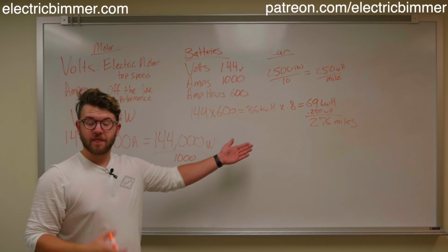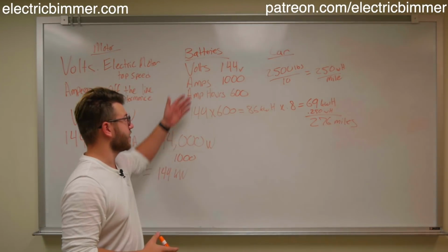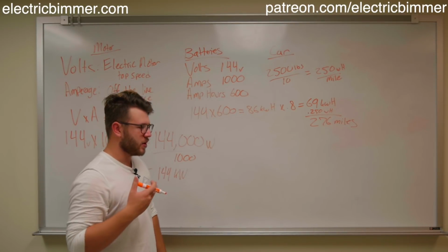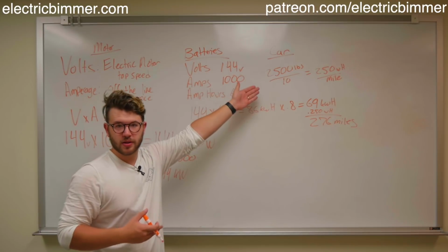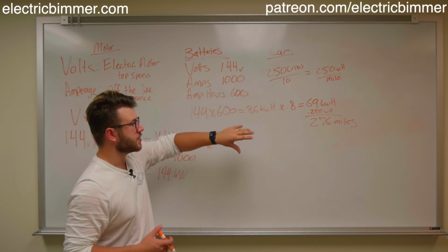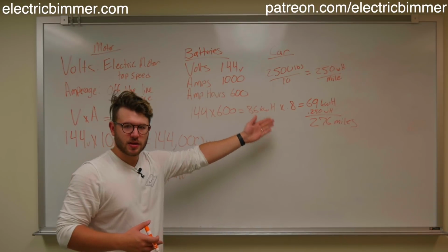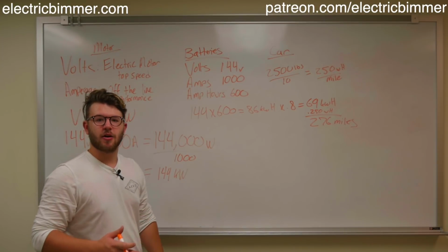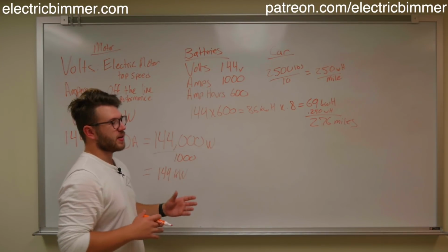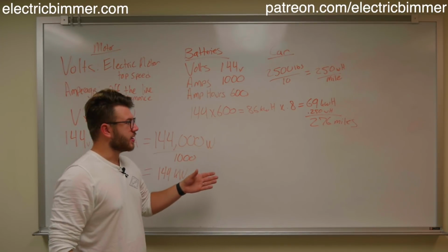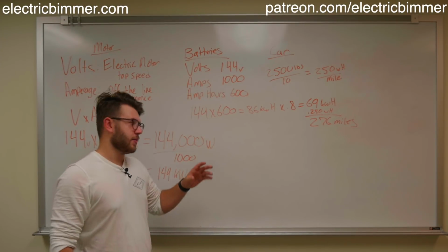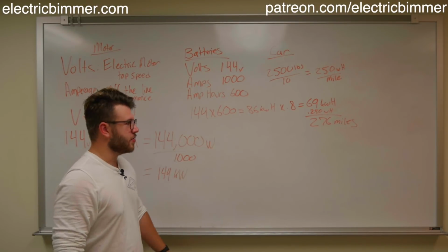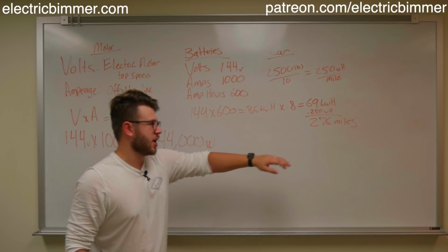So that would be a fairly significant performing car. Now, this would be a very expensive system because lithium, especially 600 amp hours worth of lithium, is going to be a pretty penny, but in a car like this that's pretty lightweight, uses less watts per mile, and is using more efficient battery technology, you're going to see a huge performance gain in your final results. So definitely keep that in mind when you're designing your car, because that's just going to be a very significant thing, the difference in battery chemistry. Again, I think lead acid's good for testing, but in the real thing, you're going to want lithium because that's going to give you a lot more range. If you did this with lead acid, this would be chopped in half.